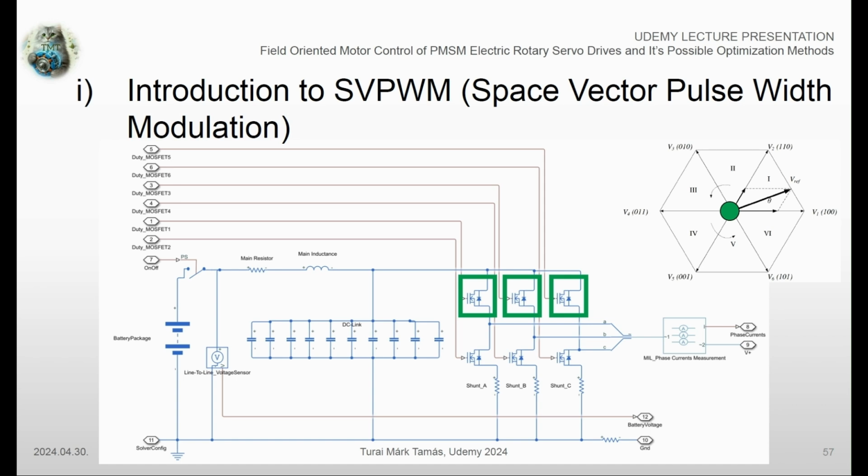In this case, the induced phase voltage is going to produce such phase currents that have the opposite direction compared to the actual state of the motor. This opposite phase current direction is going to produce a counteractive magnetic field, which will result in an opposite braking torque. The V8 zero output voltage vector is very similar to the V7 base vector that we have just discussed.